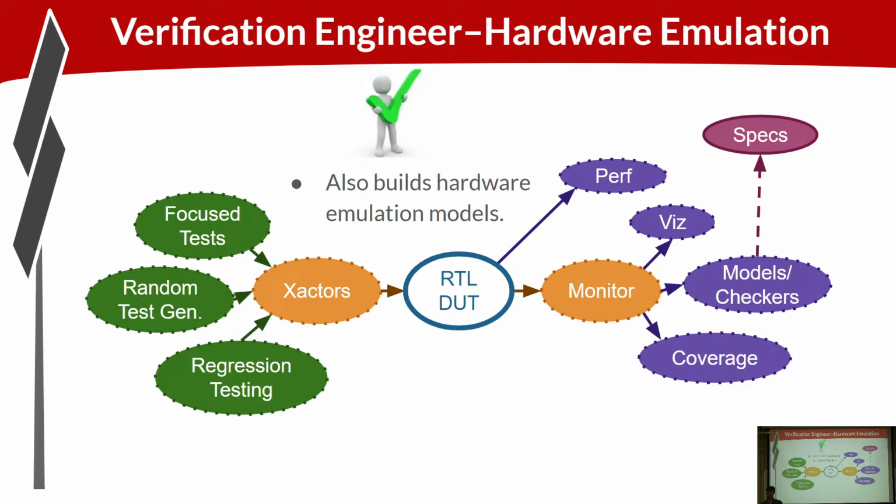Basically, you're running your design in the FPGA instead of running it in simulation. So the RTL DUT, design under test, is synthesizable and therefore can be run on the FPGA hardware. The rest of these components may or may not be synthesizable, and if they're not, they need to be run in software on a host platform.